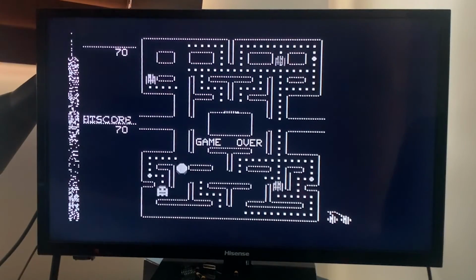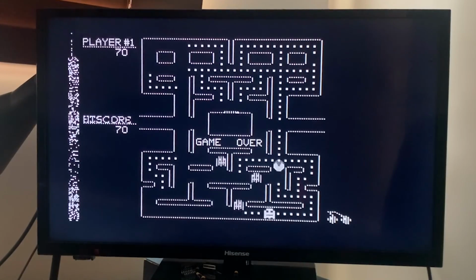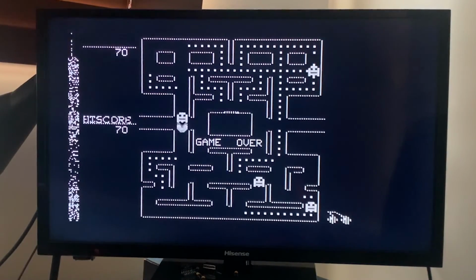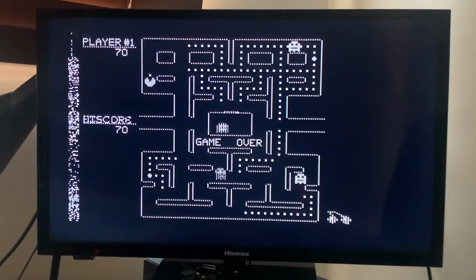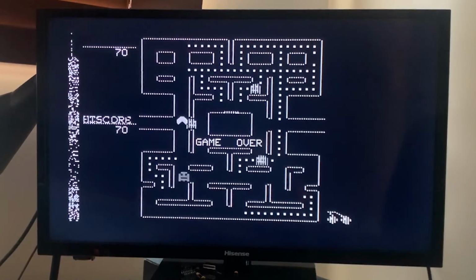Right now, the Arduino is actually just sitting there doing nothing. I've got a bit more work to do. I need to center the image and move the active signal to cover this garbage on the left of the screen. I need to get text mode and to get color to work. I'm also keen to get the keyboard and the disk drive interface to work as well.